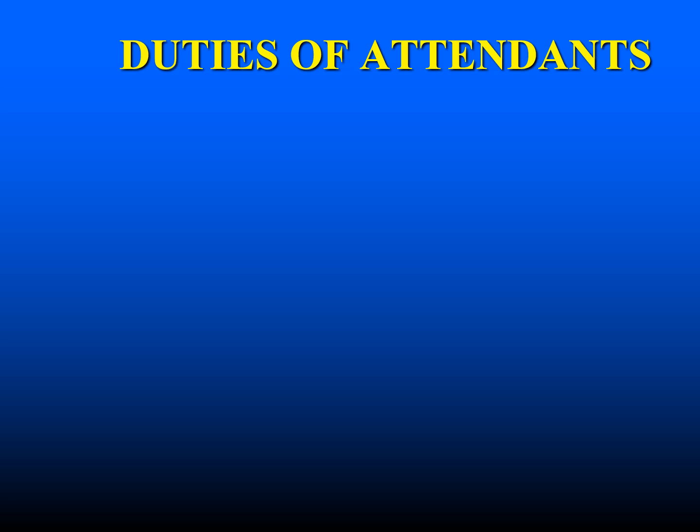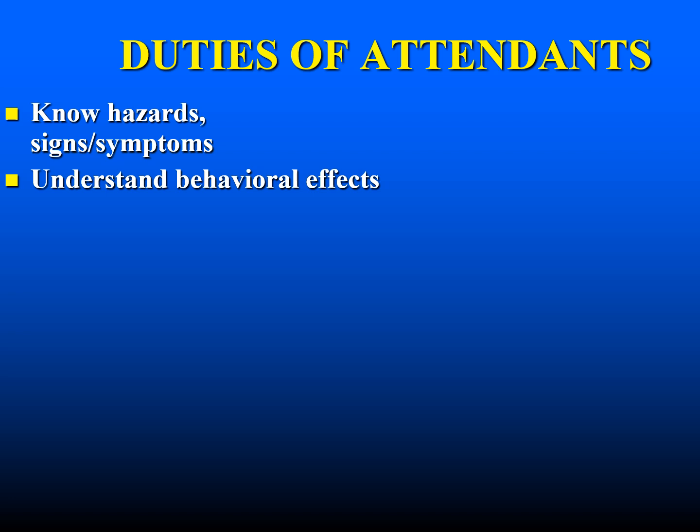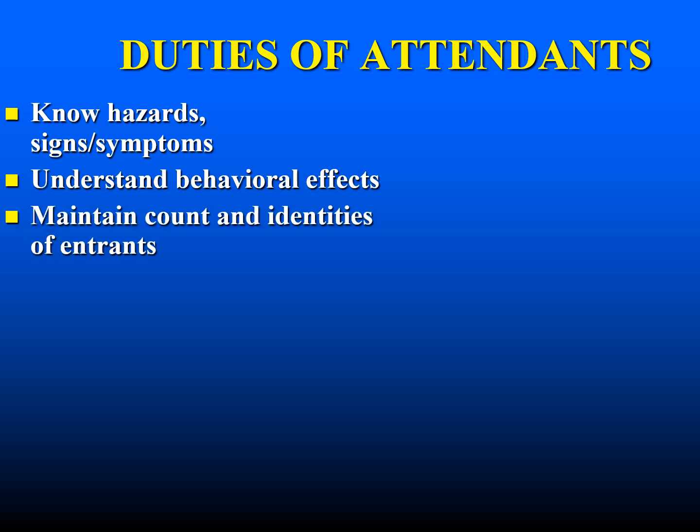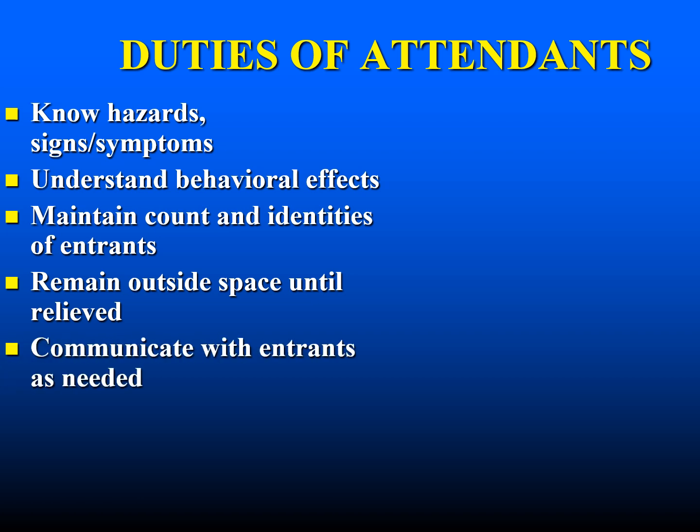Let's go over the duties of each one of these attendants. They must know the hazards and the signs and symptoms associated with known hazards. They have to understand the behavioral effects, and they have to maintain count and identities of each entrant. They must remain outside the space until they are relieved, and they must communicate with entrants as needed.